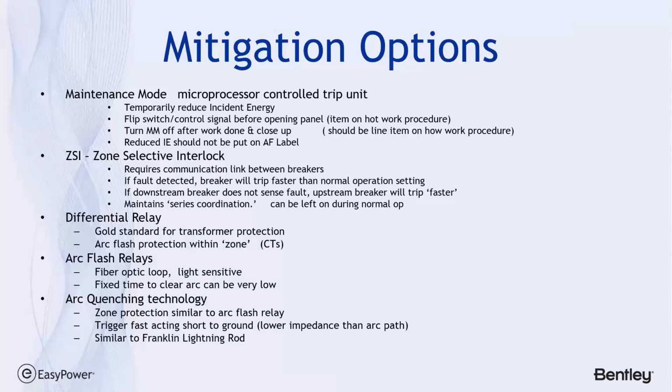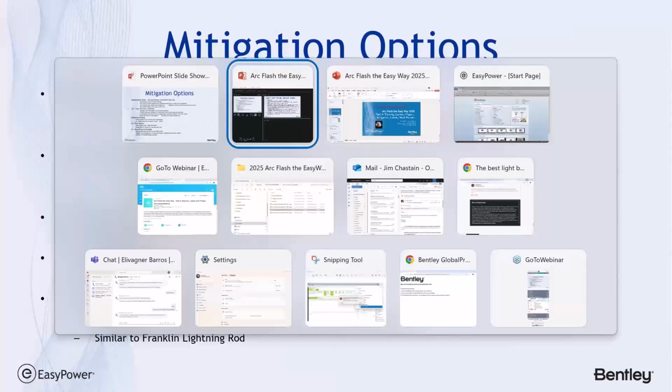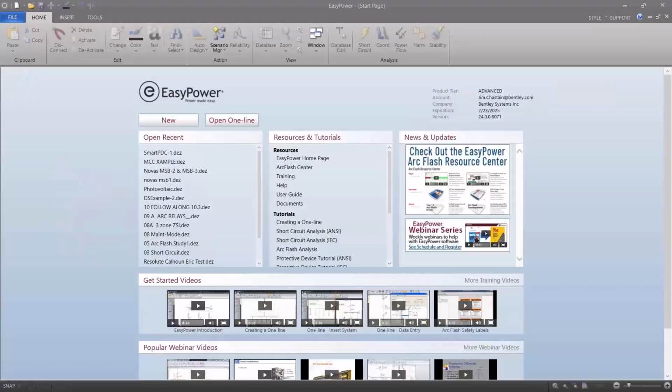And the problem is you need to turn maintenance mode off after the work is done, because if it's left in the on position during normal operations, a transient of a large load could force a system to trip. So let's talk about this more in detail.